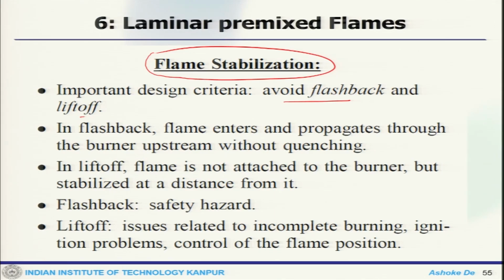The reason is very simple, because your fuel and air are already mixed before they get into a combustion chamber or the reacting system. So, this is the major source of concern, because once you have a premixed mixture which is always exposed to the reaction, any transfer from the other side, heat source or radicals or anything, can ignite this mixture instantly. That is why you see auto ignition in your SI engine, because that is a spontaneous ignition of this mixture, which we will touch upon when we talk about engines.